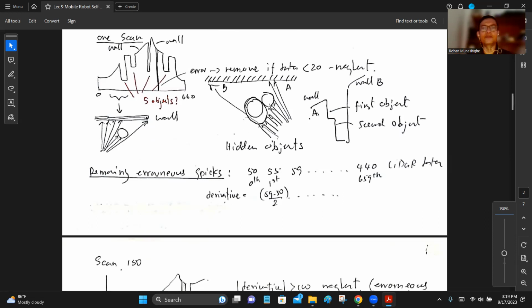And also there can be a tree behind another tree, a big tree and a small tree, like this, for example, next to each other. So in between there's no space, so that the beams hit on the first tree and the following beams hit on the next tree as a continuous thing. So if you look at the LiDAR map, you will see something like this. There's a tree, right, close by, and then there's another tree a bit farther away, right, and partly covered by the first tree. So it will look like this, 2 steps down. So you can interpret that, okay, very easily.